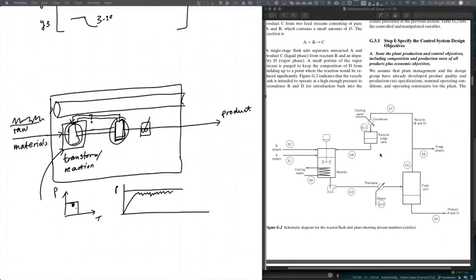If we have two different versions of events, one where we have high variance and one where we have low variance, let me use a different color. If something bad happens when we reach that bounding pressure, the system with the lowest variance allows us to operate more closely to the optimum operating conditions, right?